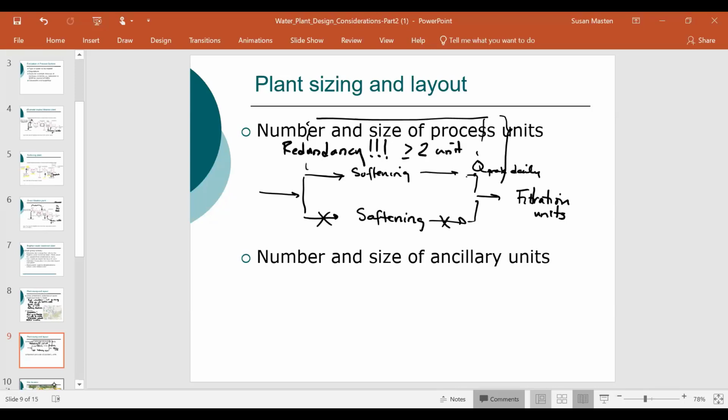And the reason was because they have these softening lagoons. They took the sludge, remember I mentioned this, and this gets pumped out into these dewatering lagoons. They also pumped the backwash water out there, and they recycled some of this water back into the plant.